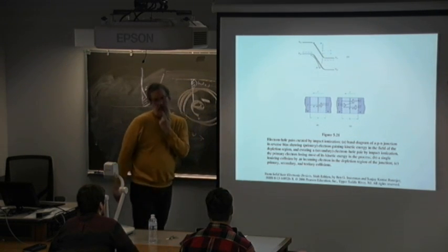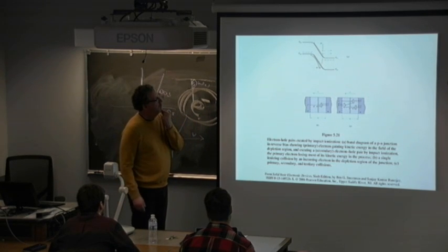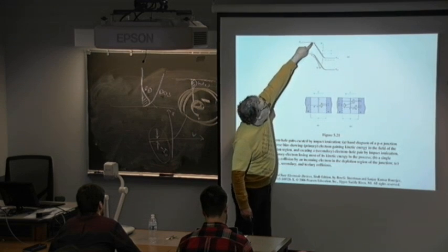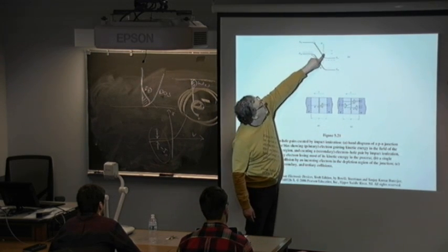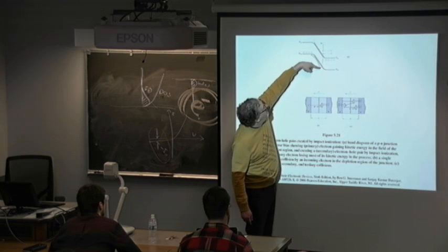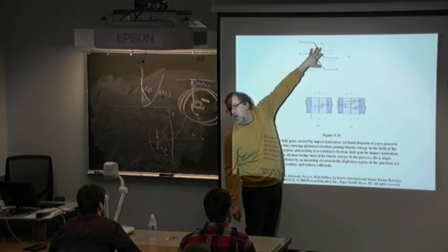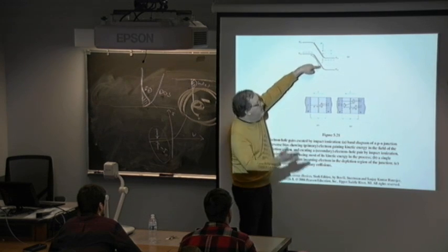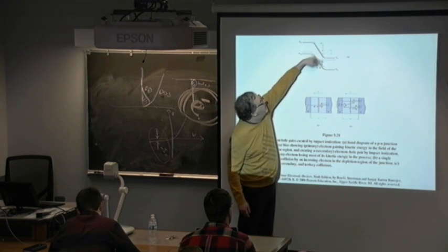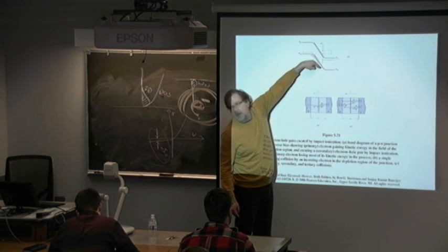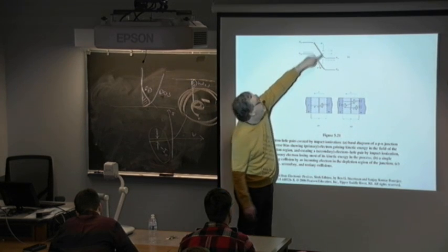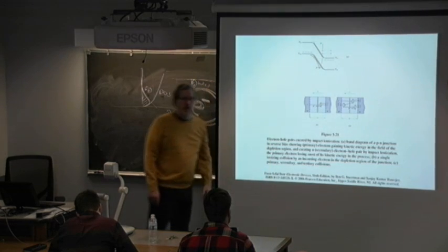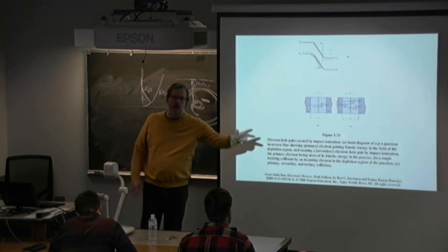Yes? So wait, an electron is moving from one side to the other, but how's it creating two again? Because it's coming down so fast, when it collides, it's going to ionize and pop an electron hole pair. By delivering that kinetic energy to the lattice, it's going to knock an electron out of the valence band up to the conduction band. So it's ionizing an electron, creating 3 particles out, 1 particle in.